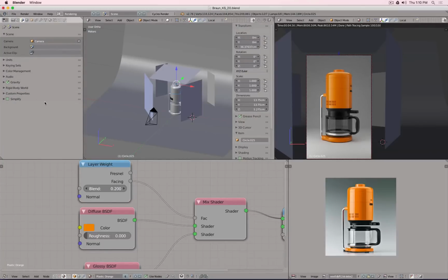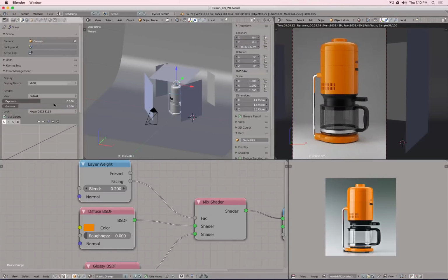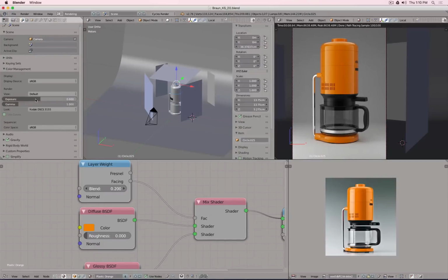You don't really want to do this in Photoshop for this reason: while in rendering we have more color information to process and to work with, when you render this, save into JPEG and go into Photoshop, you have less colors already. So the color correction you do in Photoshop will not be as good as when we do it natively inside the render engine. And that is not something that's unique to Blender, that's a general practice as well.